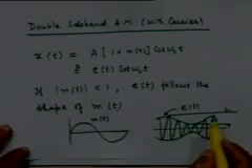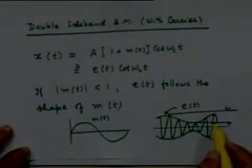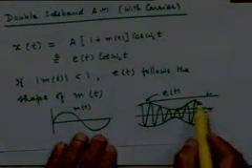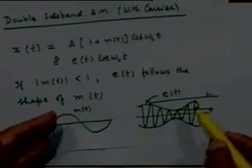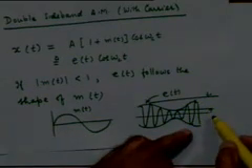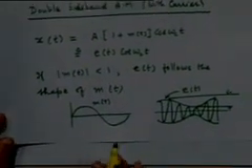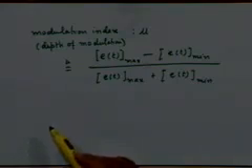So in that case, the numerator will be half of this value, which is the one-sided excursion around the denominator, which will be the mean value, right? So you can think of the denominator as twice the mean value. E max plus E min is twice the mean value. E max minus E min is the total excursion, right? So half the excursion divided by the mean value is the modulation index. Right? Half the peak to peak excursion divided by the mean value of the envelope gives you the modulation index, also called the depth of modulation.